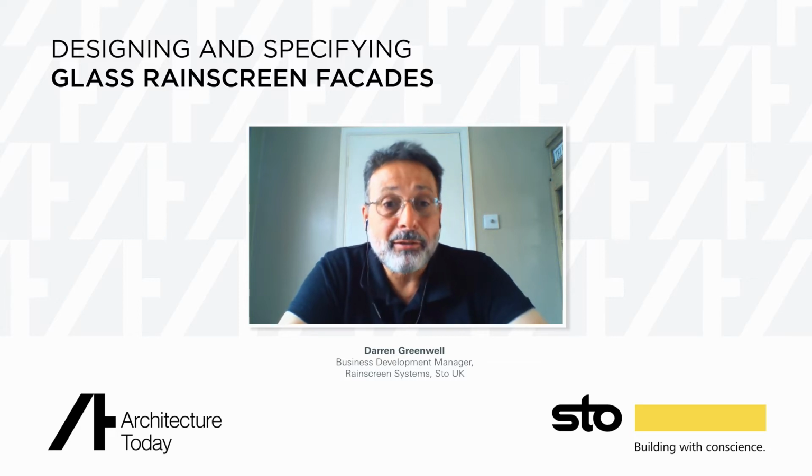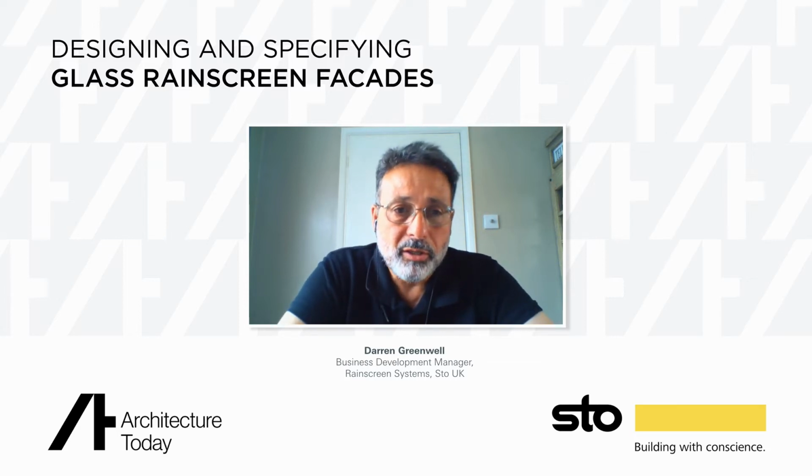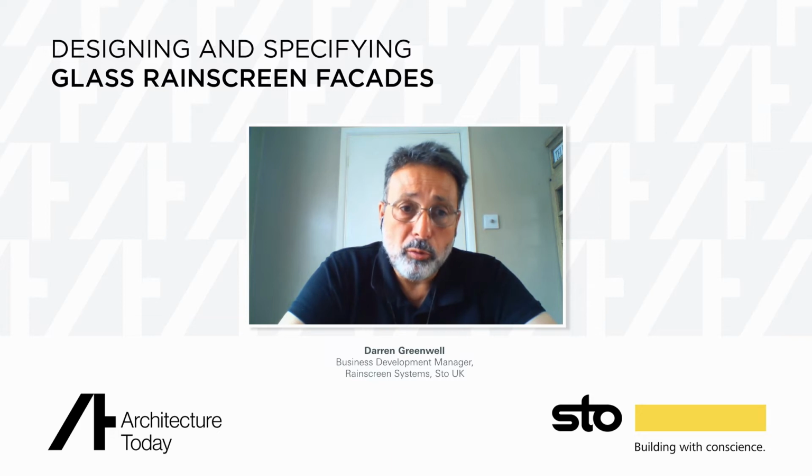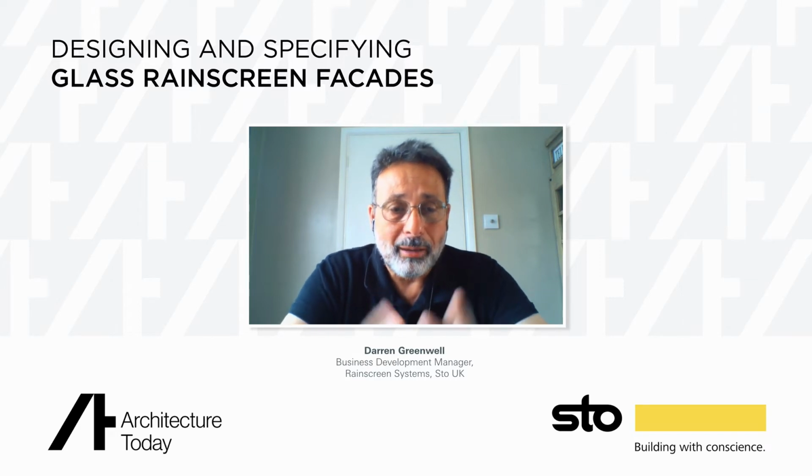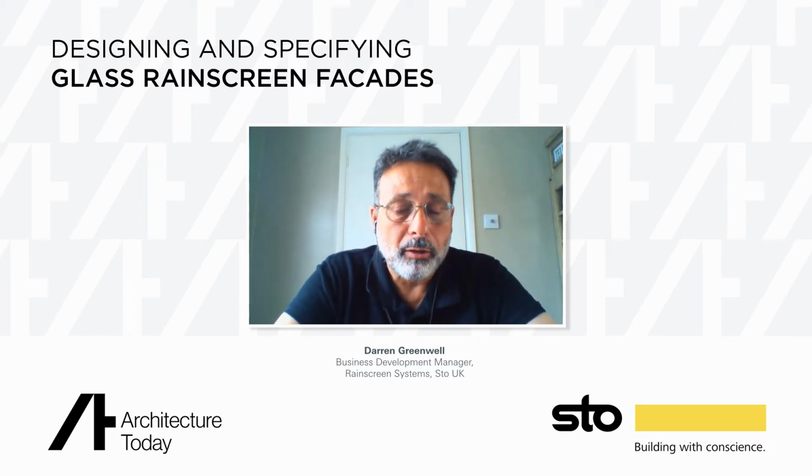The build-up of our system, once it goes on there, is initially the stainless steel brackets go onto the wall. I think the second part of the presentation will talk more about why we use stainless steel brackets. Once those are fixed onto the wall, you cut slots into the insulation and slide them over the top of the stainless steel brackets, so there's no gaps. It's just a straight cut.